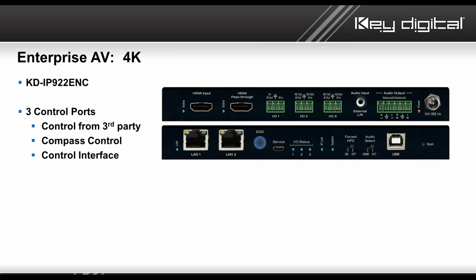And then it could also be an expansion of third-party control systems, meaning we do publish in the owner's manual for the product how to speak to each and every individual unit on your system, how to tell it, hey, port number 1, 2, or 3, you're either going to be IR or RS-232 or voltage, and here's what you need to send right now. So it's an expansion to any third-party control system. If you've worked with Global Caché before, think of this as a Global Caché that's built into an HD over IP system.